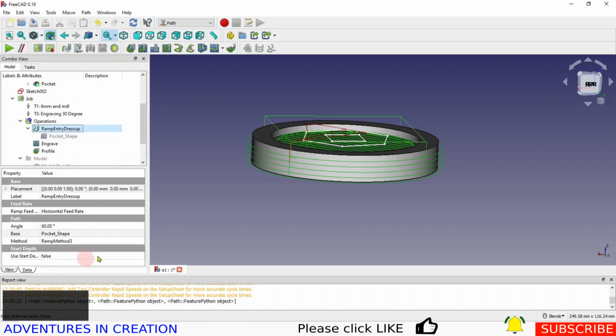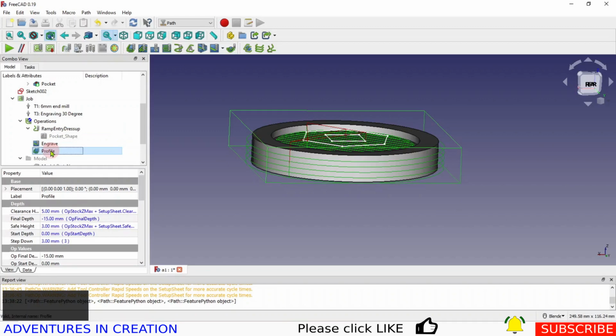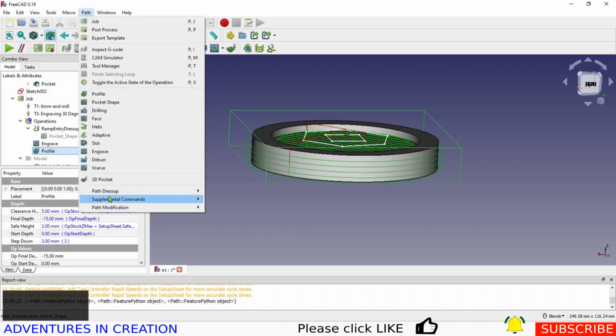I generally just leave the default, so ramp method 3, 60-degree angle. In this particular case, what it's actually going to do is back up a little bit and cut down at an angle. Now, on the engraving, I don't want to do that, so I'm not going to change the engraving. But for this outside profile, we need 2 things. So we want that ramp entry, but we also want tabs. So again, it's a path dress up,